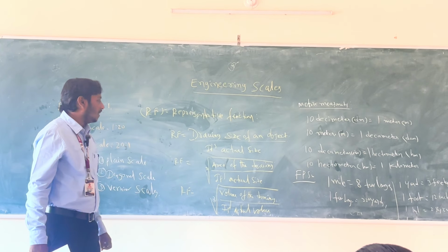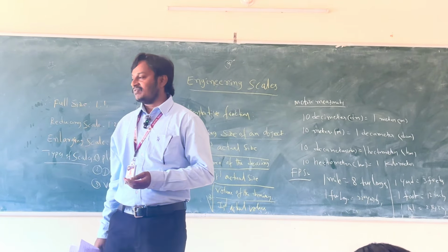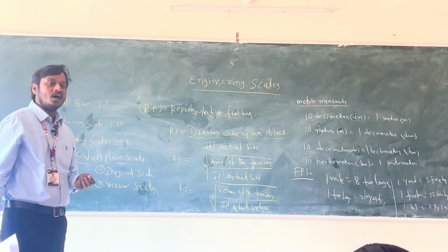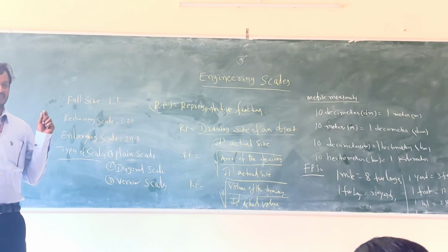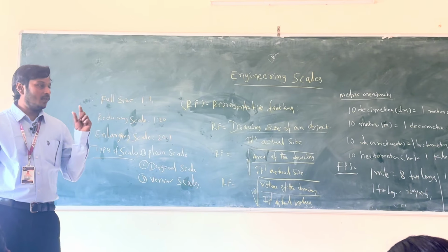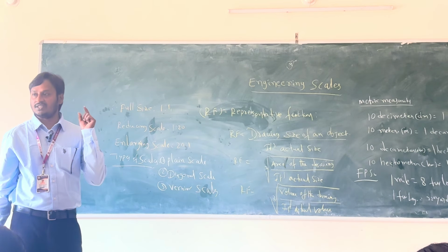Next, the length of the scale. How to find the length of the scale? Length of the scale, L, is equal to RF into the maximum length to be measured.